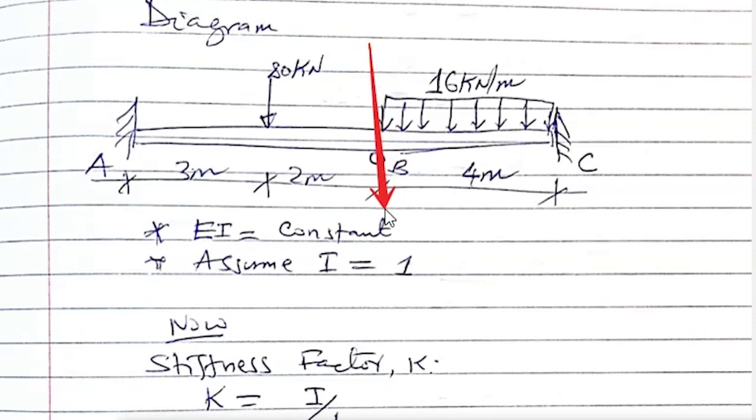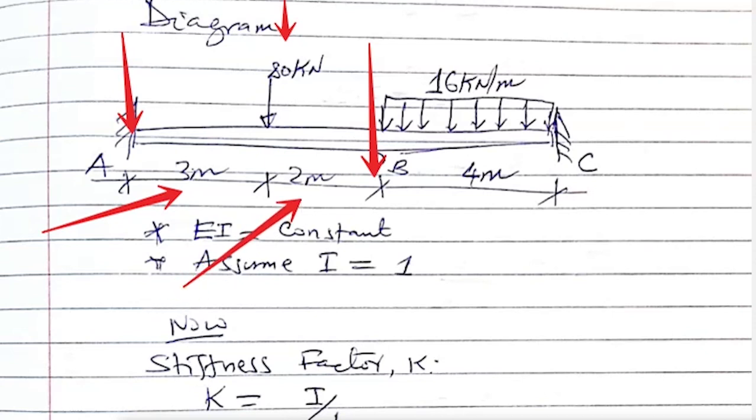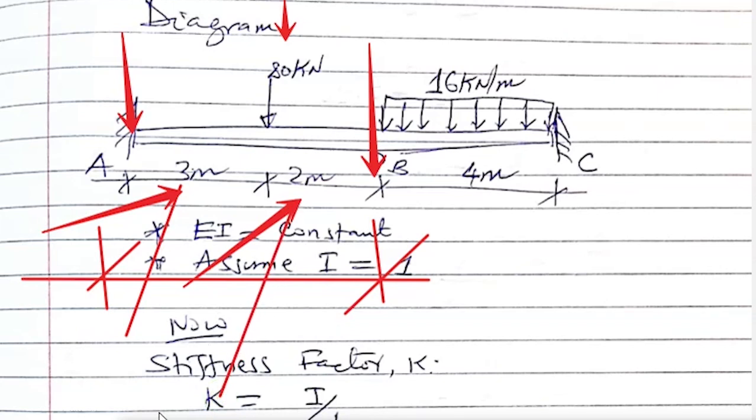this is considered a fixed one from B and A with a concentrated load as a point load, which is between this length, and the total length should be the summation of these two values, the value of 3 meters plus 2 meters, which is a length of 5 between A and B. So once you calculate the fixed end moment, as I said there, you can get the fixed end moment from the left and from the right, this way and this way.